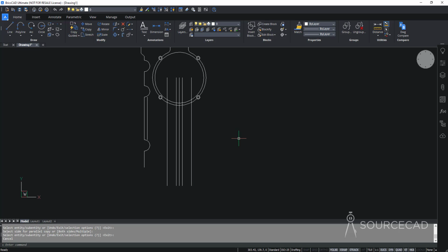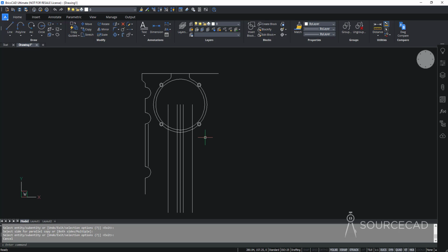Now let's add the horizontal line here. Well, in this case, before I add that horizontal line, I think it's better if we just make a mirror image of this part over here. So let's just select it all. So I'll just select all of these here, excluding this line, and I'll just make a mirror image of this. So I'll go to mirror, I'll click on this midpoint, and then I'll click right here on the center and press enter, and I've got the mirror image here.